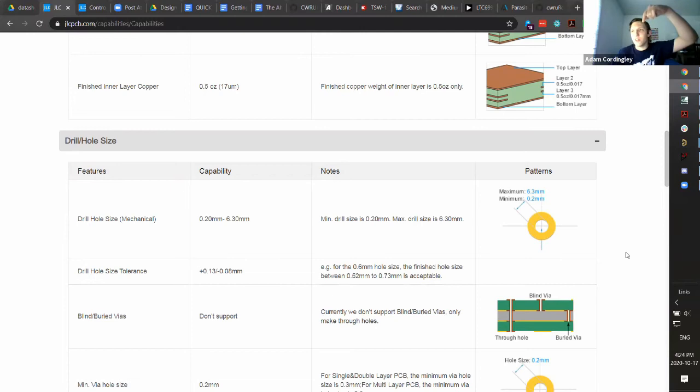So basically the way you do it is when they're manufacturing the PCB, after they've laminated your layers together, they drill through the whole board, and then there's a final step where they plate everything up. They add a very thin plating to everything. That plating process gives you a plated through hole, and those are your vias. So a via is a plated through hole from the top of the board to the bottom of the board, and through all the layers in between for that matter.